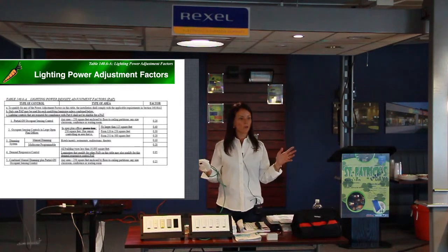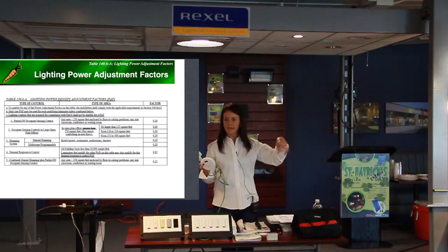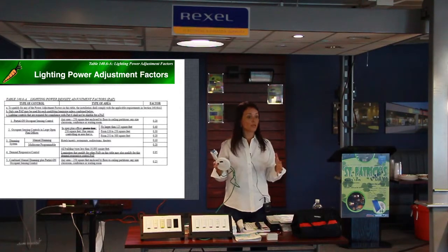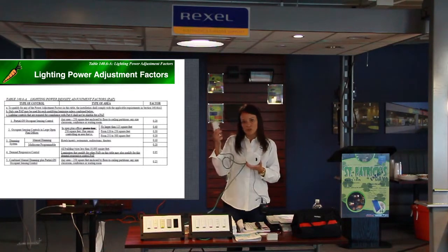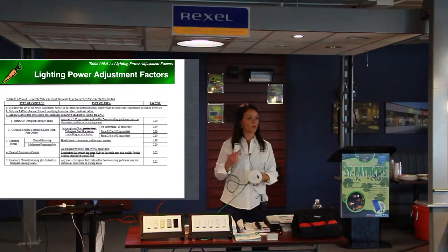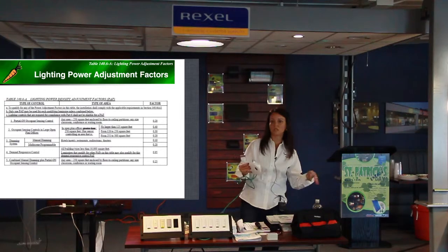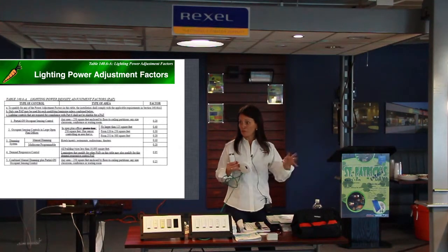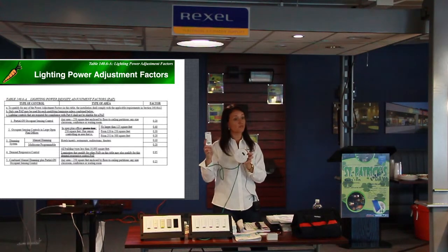Most of the times people are happy with half of the lights. If you give people 2 switches in the wall, 90% of the time they would flip both switches to work in that space. If you give some level of lighting, 70% of the time people will not even touch the second one. That's why in code design there's all kinds of studies done about bi-level and partial on. And that's why manufacturers, instead of having a complicated commissioning system where I have to have a factory specialized field service guy to assign all the lights, we are trying to make it simple. Plug and play, and out of the box it works.